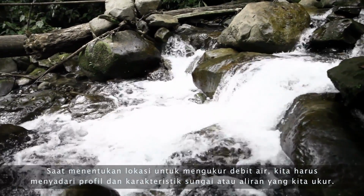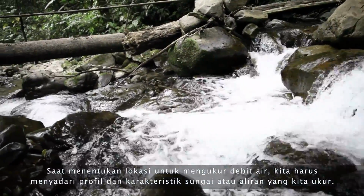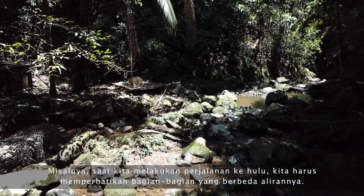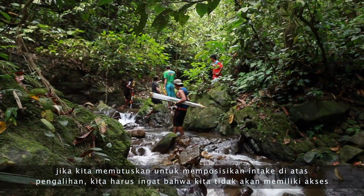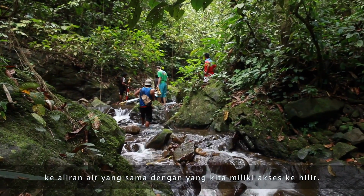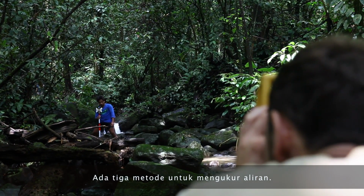When determining a site to measure flow, we must be conscious of the profile and characteristics of the river or stream we are measuring. For instance, as we travel upstream, we must take note of portions where the stream diverges. If we decide to position an intake above a diversion, we have to remember that we will not have access to the same flow of water that we would have access to downstream. Now, there are 3 methods of measuring flow that we will discuss here today.